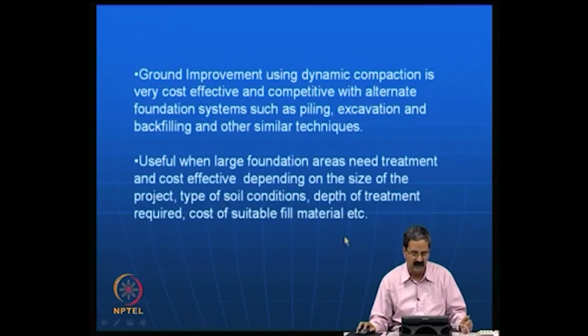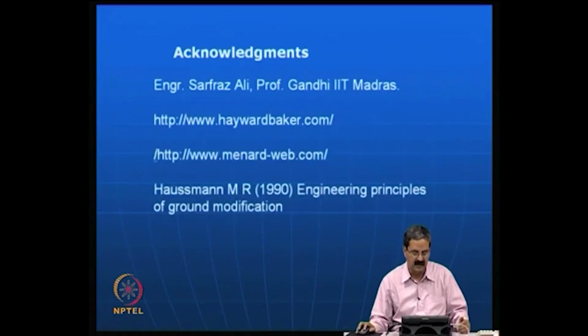And the cost of suitable fill material is also important. In some places you have to borrow material, like in the previous case studies we saw that to construct the airport you had to bring soil from nearby islands. So the possibility is that they could be expensive. So one should really weigh many alternatives and decide which is the best.